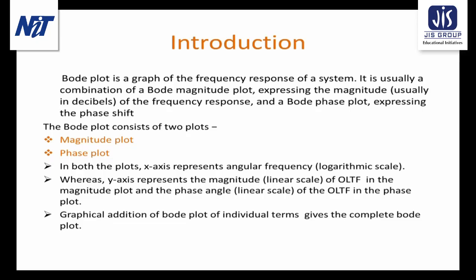And this plotting of magnitude and phase shift with a logarithmic scale is known as the Bode plot. Now, this Bode plot gives us the information more clearly than the corresponding linear plot. The information compressed near the origin in a linear plot can be easily visualized in the Bode plot, as the logarithmic frequency is magnified near the origin in case of the Bode plot.